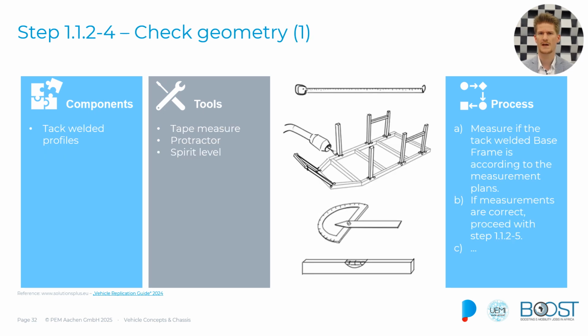So we have now these tack welded profiles. We again use our tape measure, protector and spirit level, and we look if everything is in the right angles, if everything is at the right position. If so, everything is fine.